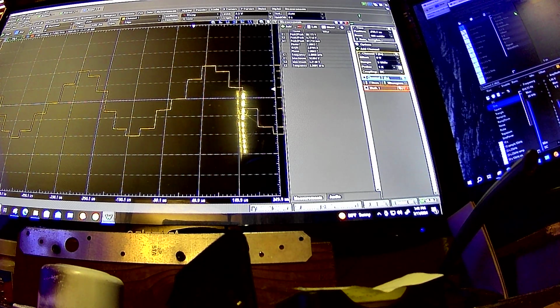Really, I guess it can do all the levels this thing can do at maximum. But at 4,000 levels, just to make a ramp wave would require 4,000 voltage levels. If you wanted to do a triangle wave from peak to peak, that would be 4,000 to rise and 4,000 to fall. So that would require 8,000 samples to fully take advantage of that resolution. 12-bit up, 12-bit down, for a full waveform.